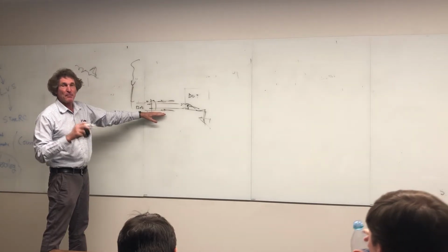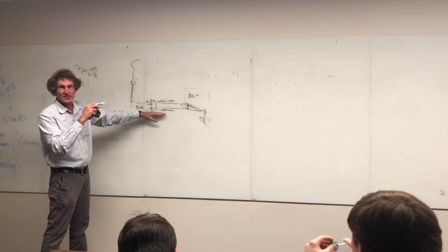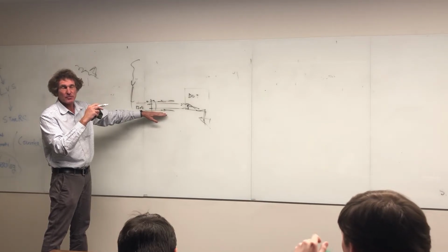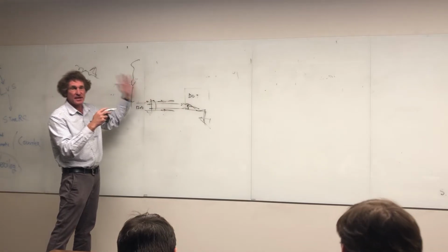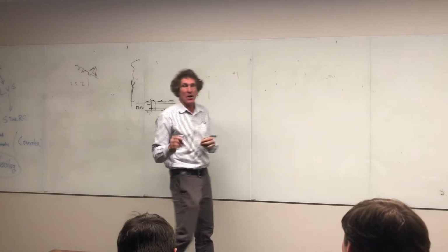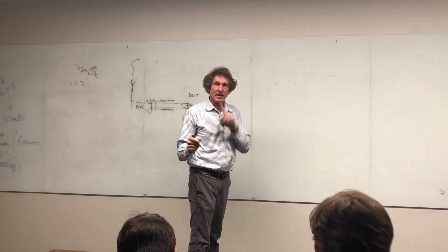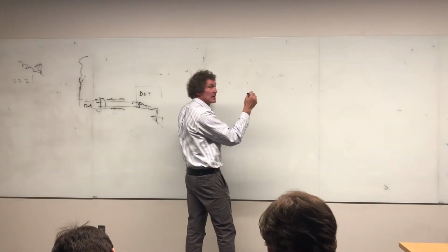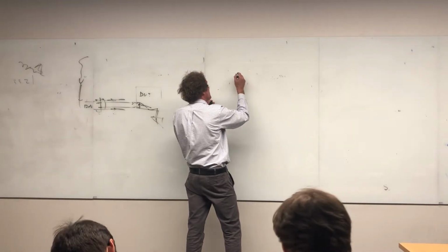I told you about ball lightning just because I thought it was an interesting thought. But the real problem is just a strike right there. It's called a cloud-to-ground strike. So how do you stop it? One of the easiest methods you can use, if the common mode current isn't too high, is this. It's called a choke coil. It's a common mode choke.